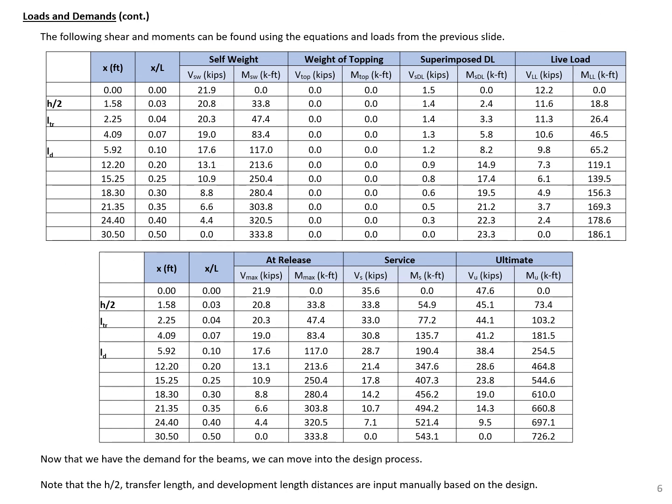We can plot these two equations along the length of the beam at different sections and with different loads, and that's what I'm doing here in these tables. You can see the x value is the distance from the left edge. We're only showing half of the beam because the beam response will be symmetrical.